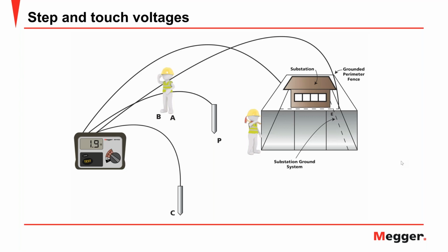With that, you can get the resistance measurement and then plug that into Ohm's law and calculate what the voltage would be in a maximum fault situation. The current that you use in Ohm's law would be the maximum fault current that could occur. And you want to then have your voltage lower than 50 volts for human safety, or now it's becoming somewhat more rigorous, and so sometimes you'll see 40 volts in the literature.